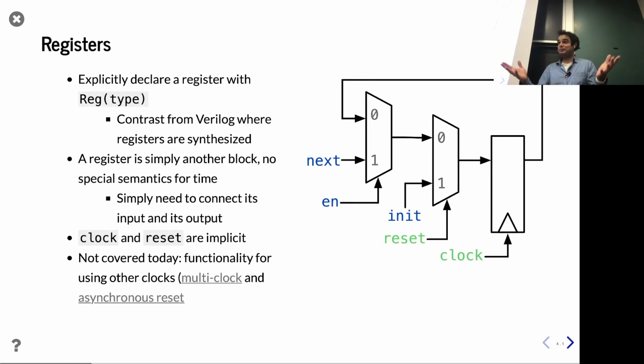And so let's talk about registers. Registers, of course, are how we store things in hardware. Usually we think about just the thing on the right: a register with an input and output, perhaps labeled in your hardware class as D and Q. But of course, there's a lot more to it. The register has a clock that determines when it reads input. For Chisel and for this course, we're working exclusively with what are called positive edge-triggered flip-flops. That is, on the rising edge of the clock is when we read the input. Otherwise, it ignores the input, and the output is continuous for the entire cycle.